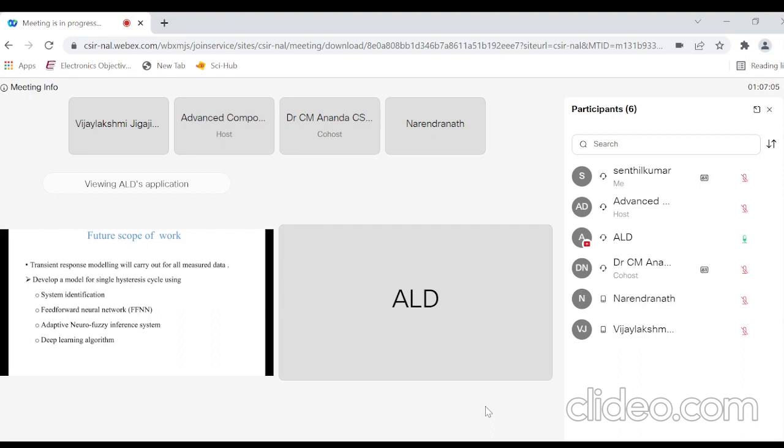Because this is engineering, no? You can't keep one number for all frequencies. At high frequency the data is coming very fast, so there you may require more data points. When the fatigue cycle is running at lower frequencies, you may require to sample lower, and you are overloading the machine by taking 10,000 points. Yes, sir, that is my question.